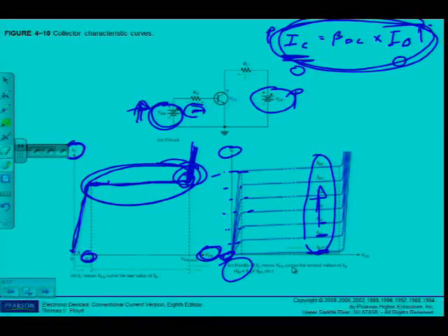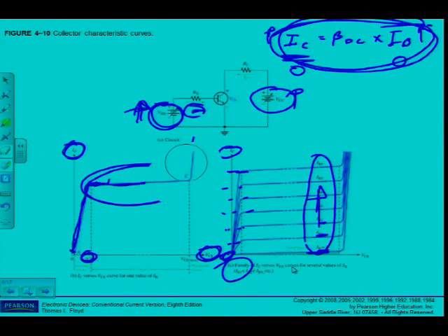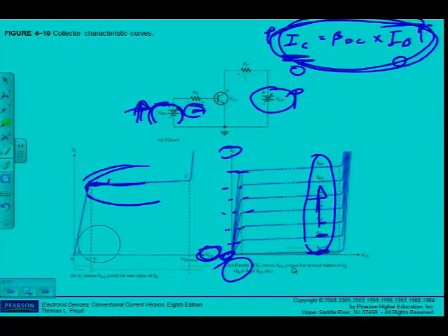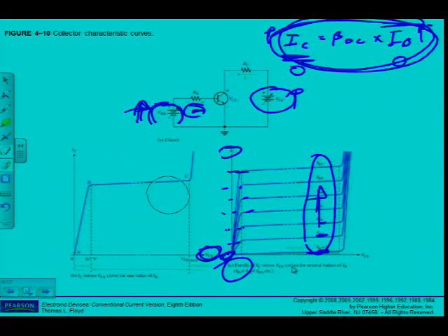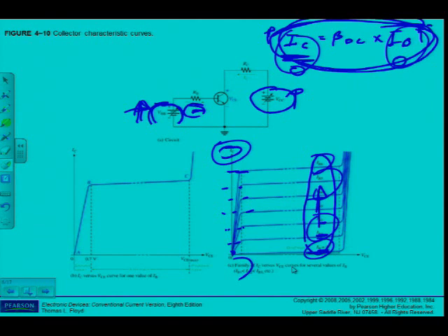I just want to clean up here a bit, the characteristic curve of the transistor here, for IC against VCE. Now we've seen that for different IBs, I will get different values of IC. But if IB is equal to 0, then of course IC will also be equal to 0. So that's one of the parameters, let's say the parameters for cutoff.